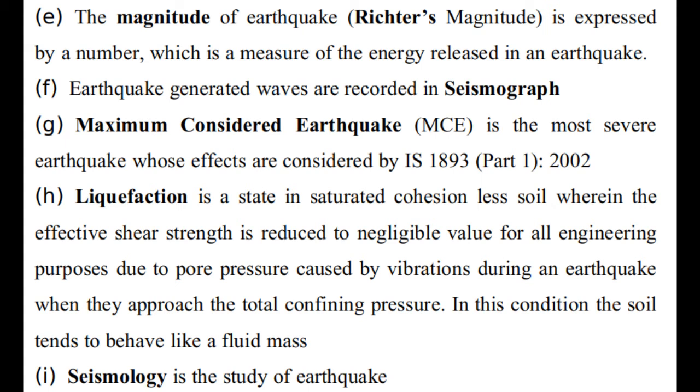Here I just want to tell you that this question, liquefaction, has also been asked in GATE architecture. You can also see my GATE videos for the architecture subjects. There you can see that one year this question has come, what is liquefaction. So let us understand it. It is the state in a saturated cohesionless soil where the effective shear strength is reduced to a negligible value. That means it becomes almost zero for all engineering purposes.